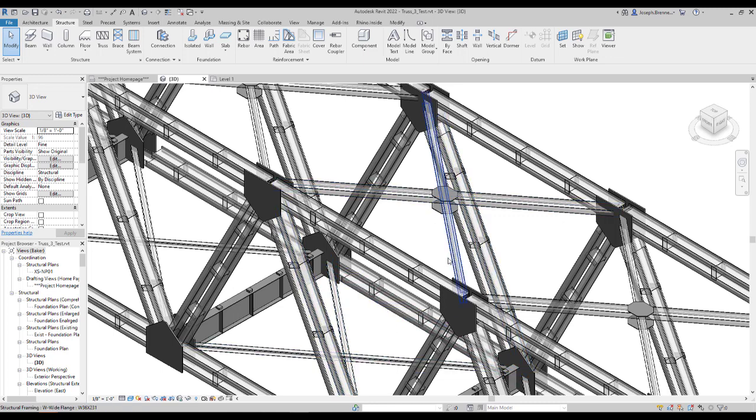What made this truss interesting are some of what we call double sections, where we're welding two W sections together for strength instead of making custom sections. You can also see some of the struts coming up through there as well. A very interesting structure.